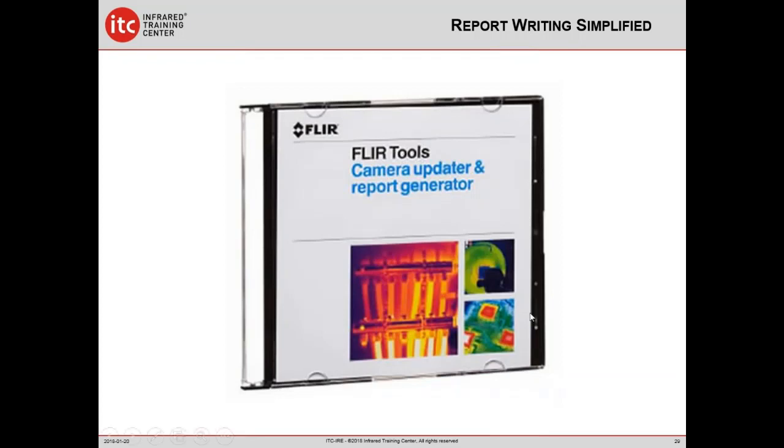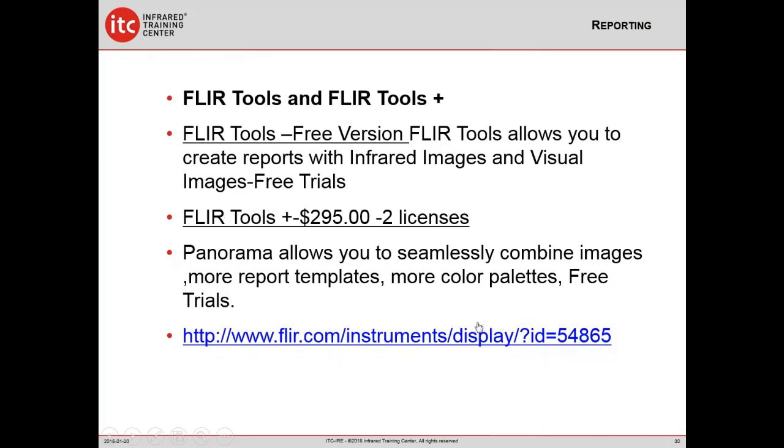Of course, FLIR Tools is a radiometric software. Radiometric meaning that when you take an infrared image with an infrared camera, it not only captures the visual part, it also captures temperature. So in order to extract those temperature readings or to thermally tune the image, you're going to need a radiometric software. FLIR Tools fills that. It is a great software to fill all those applications.